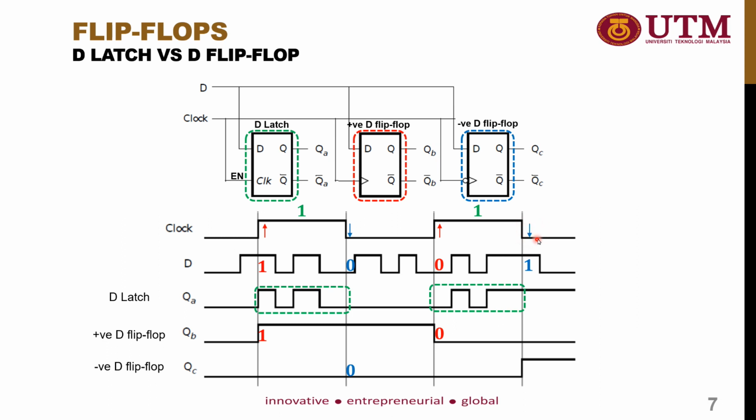So this is the next falling edge, which is the input going from 1 to 0, the falling edge, and then we observe the input D, which is equal to 1. Therefore, the next output of the negative edge trigger D flip-flop will become 1 because the input D is 1.